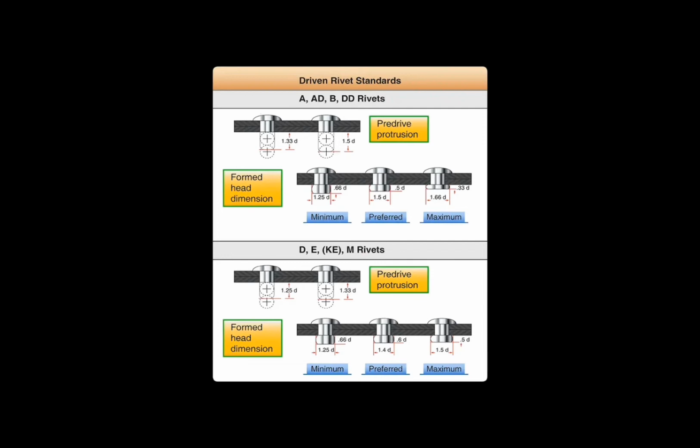What procedure should be used to prevent damage to the hole when drilling through plexiglass? Backed with wood, as drill breaks through underside feed slowed, drill bit should be modified to a 60-degree tip angle.